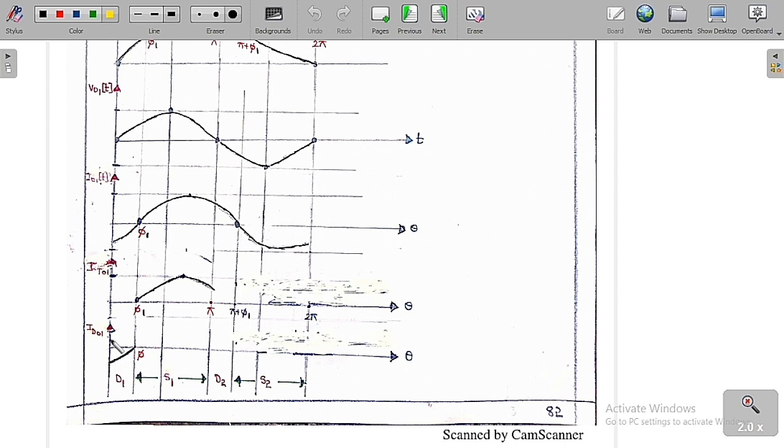As it is actually a negative value, you have to take it in the positive sense. So it will be a positive value, because only positive values are present in the current. Whenever the diode D1 is connecting, the current in the diode is the negative of the output current, so the negative has to be flipped and will appear upper here.